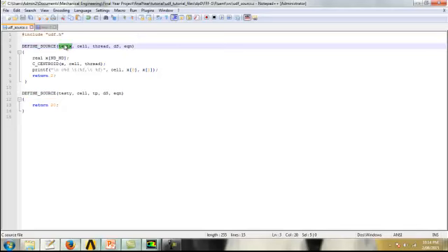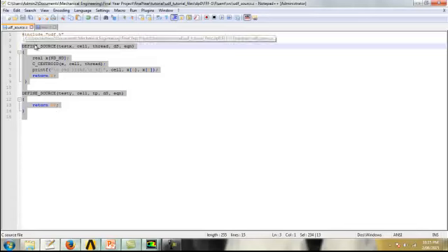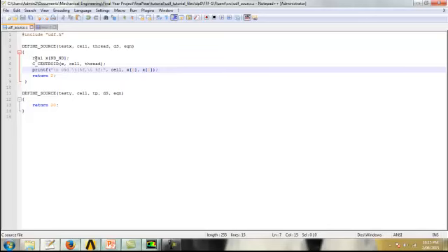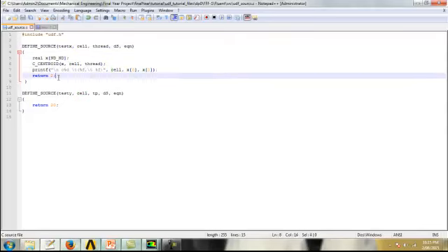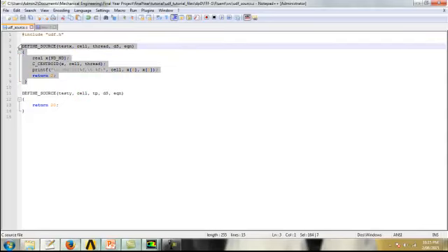Whatever you put here is going to be the name of your function in ANSYS. So once you load this in, you'll see test X, hopefully, and test Y. You can define as many user-defined functions per source file as you want. Then often what you'll want is the location of the actual cell. This gets called for every cell in the finite element method.